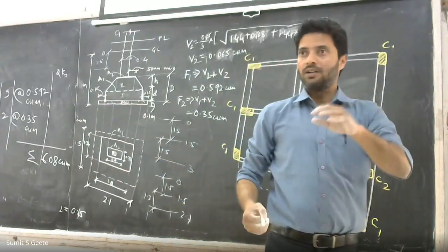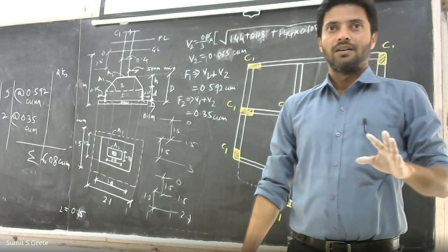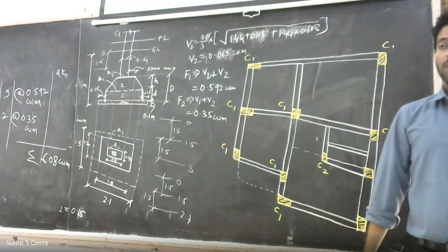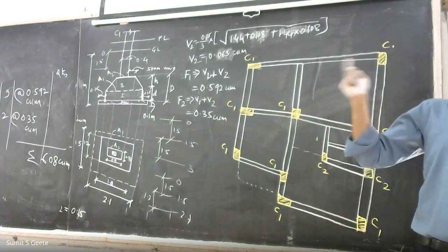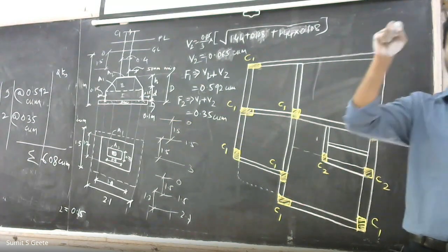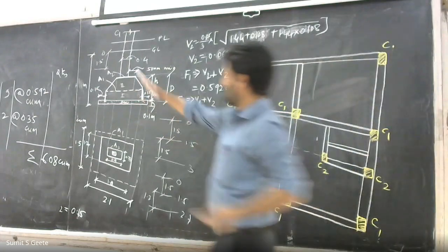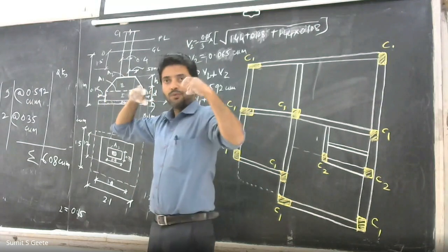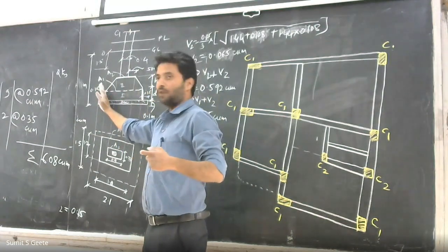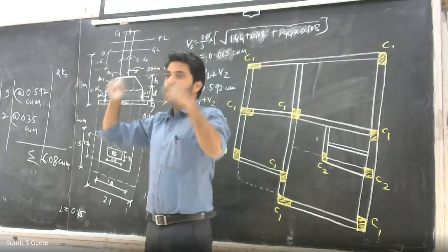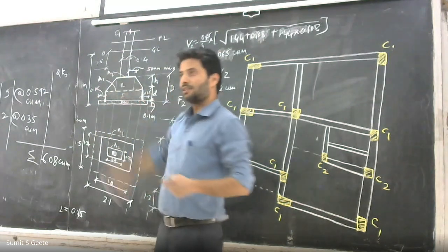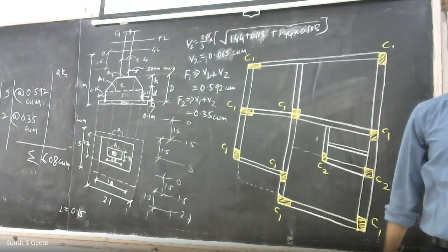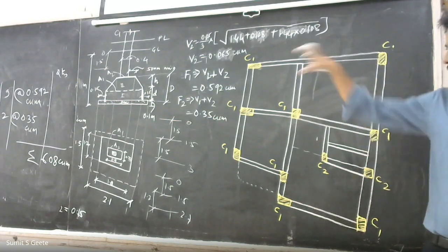This is again a point. Calculation is easy: H/3 A1 A2 A1 into A2, whatever. But practically, how is this footing going to be cast at site? Because we are not placing any kind of shuttering material over here. What we will do, we will place the shuttering at this point and this point. The second point is how we are going to do the compaction of this concrete. This is the second point, how we are going to do the compaction. Clear? So these points are essential.